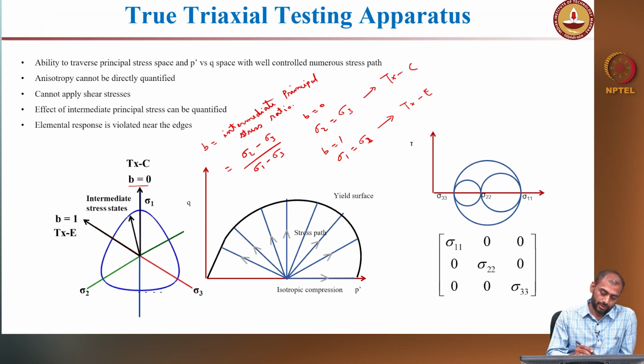So you have triaxial compression. This is the octahedral plane or the deviatoric plane, which I have discussed in the previous slide. It's perpendicular to the hydrostatic axis. So after reaching a hydrostatic axis, you can apply a triaxial compression test and move on this particular line, right. Triaxial compression, sigma 2 equal to sigma 3. Similarly, if you are performing a triaxial extension test, you move on this particular plane and then locate your failure point, right.